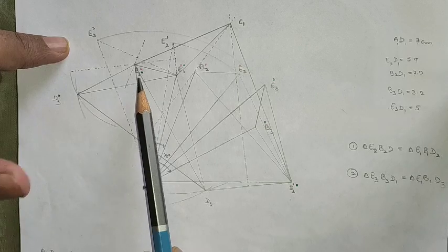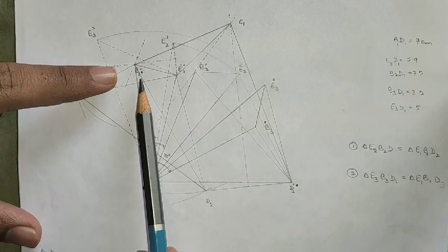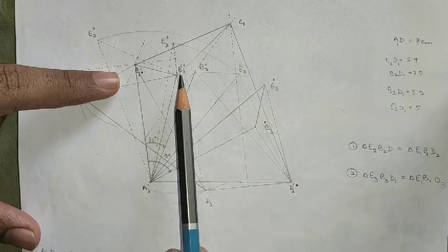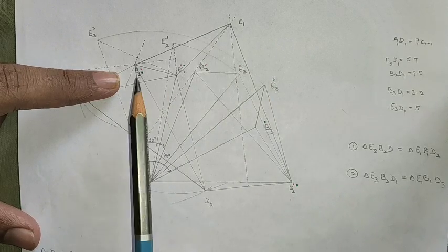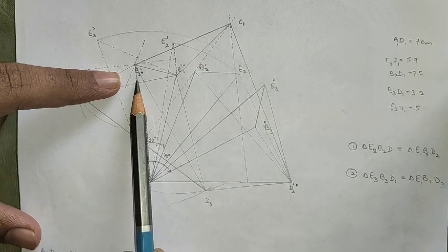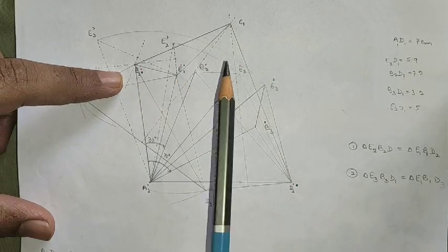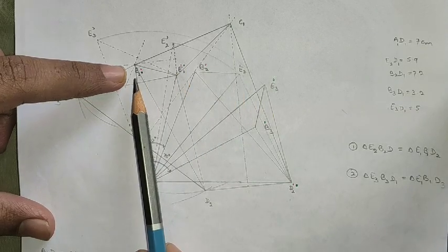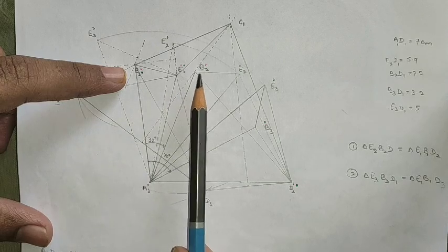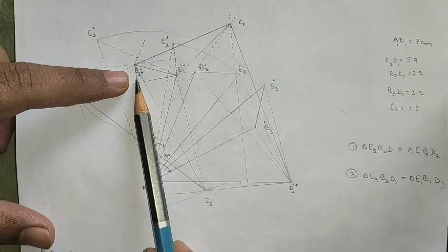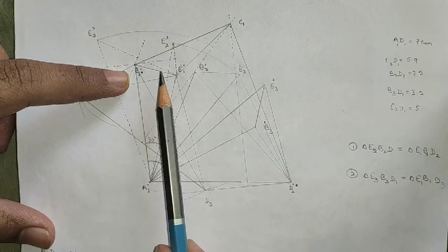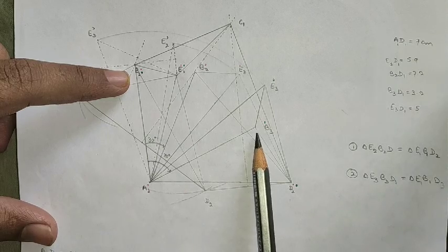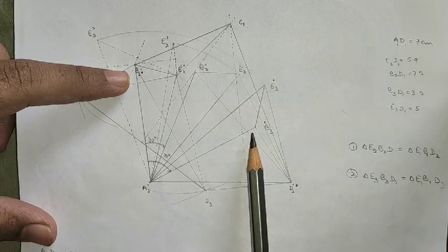Now my purpose is to determine the other points also, but before that we are determining the B1 position in the 3 respective positions. Similar to E1, E2 and E3, we are determining B1, B2 and B3. How can we determine it? Same as before, we rotated E2 and E3 by an angular displacement, so now we are reversing it back. B1 we are reversing by an angle of 30 degree to get B2 dash, and again B1 is reversed back by 70 degree to get B3 dash. A1 B1, A2 B2 and A3 B3 are of the same length at different angles.